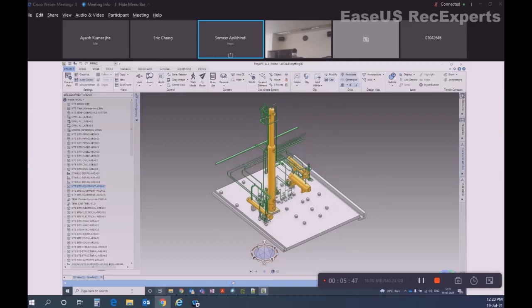At the bottom, you can see there is a caption for this current view, 3D view 1, draw list 1. That means there is only one view at this moment and there is one draw list active. So there can be multiple draw lists and multiple views. You need to associate a view with a draw list. Let me make it plan in this view.